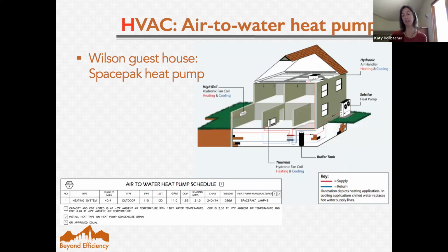The neat thing about the Sanden is it has such high output, and it produces such a high temperature hot water, 149 degrees is kind of the default, that in low load applications it can be used for heating. But like Kara was saying, with the Sanden the efficiency is very dependent on having a cold return temperature to maintain that temperature striation in the tank. So the engineering with a Sanden is a whole other kind of art and science compared to these other systems, but there are a lot of really good applications with it.